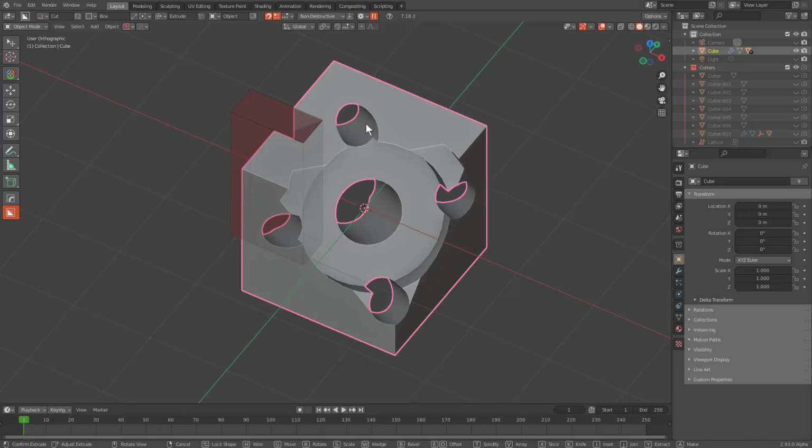And if I move it up, it continues to go down. This is because it requires that you put the mouse cursor specifically near the origin of the extrusion start in order to reset the extrusion back to 0. This can be something a little bit daunting to new users, and for that reason, tapping Alt will actually revert the extrusion system back to the previous way so that users can easily take their extrusion back to 0 and constrain their extrusion operation back to a simple up-down maneuver.